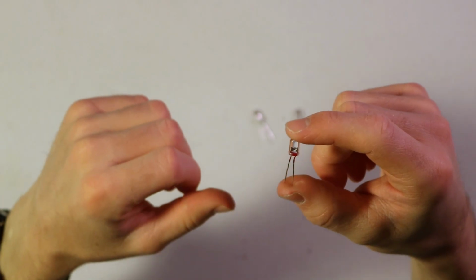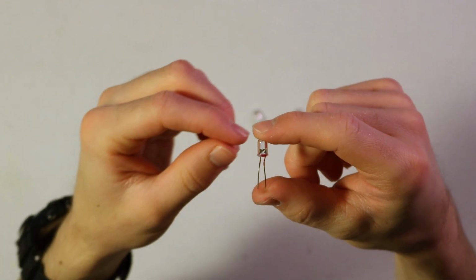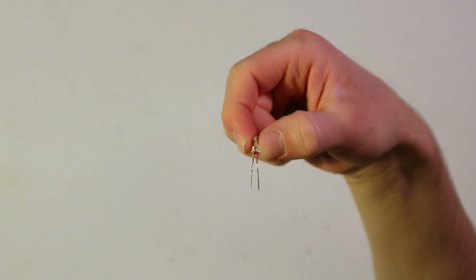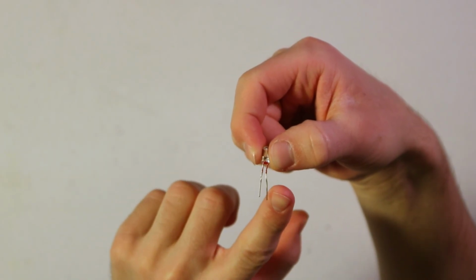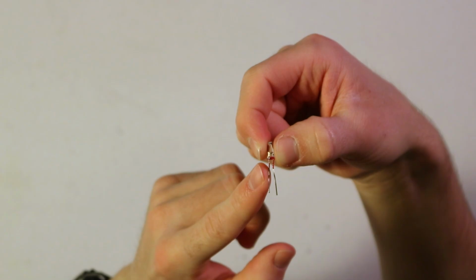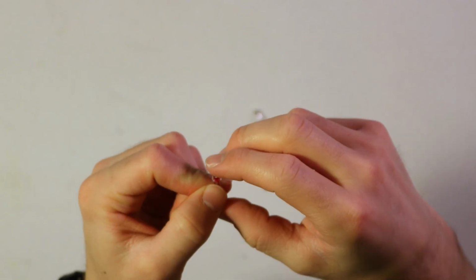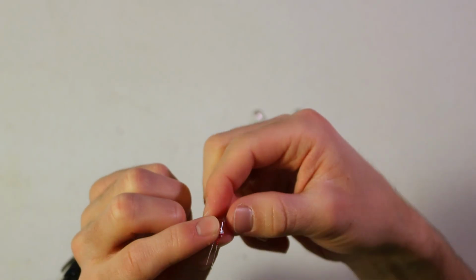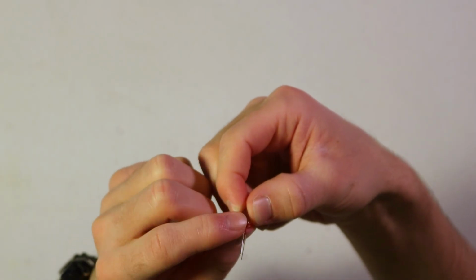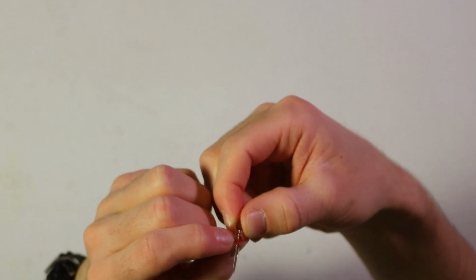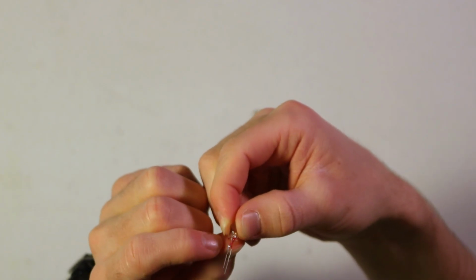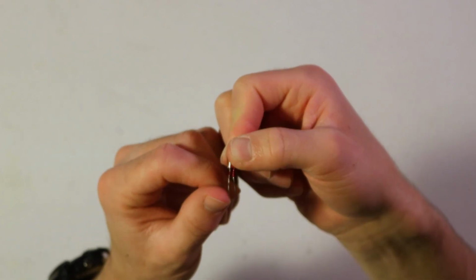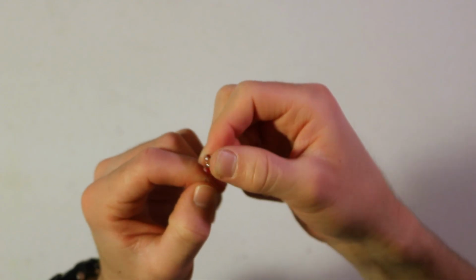The color of the LED is going to depend on the materials inside the LED that make it work. If you look closely at an LED, you'll see that the 2 leads are not the same length. Let me hold it like that, and you can see one lead is longer. The long lead is the positive lead, and the short lead is the negative lead. You can also tell which is which if you feel on the side. You're not really able to see this on the camera, but if you feel on an LED, right on the edge, one side of it is flat, and the flat side is on the negative side as well. So long lead is positive, short lead is negative, and the flat side is also negative.